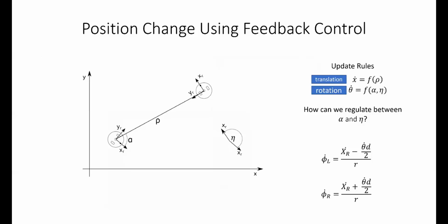So how far does my robot need to move forward? And how much does my robot actually need to turn? And this is a little bit of a lossy signal. If we look at this example on the left, this robot has to rotate, then drive, and then rotate again, in order to follow the shortest translational path. If we say that the amount of translation is just this straight line distance, well, if we solve these things at the same time, we'd expect the robot to take an arc that's going to get it to its final position.